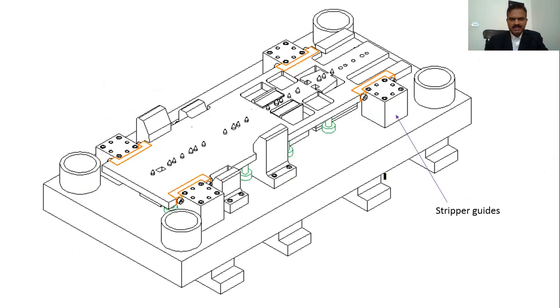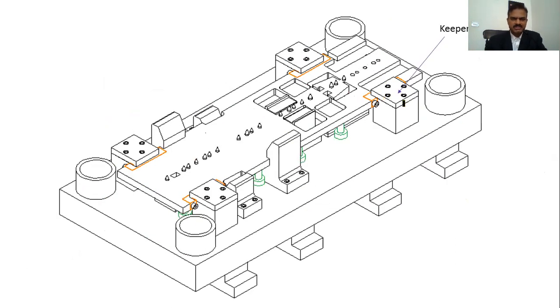You can see the stripper is dropped down now. But in the same way you can move it up, right? Because nothing is stopping it from coming up. So you need to put a plate here that you can see in the next drawing. So this is the plate. See, it's a keeper plate or cover plate. It will prevent it from moving up or dropping down if it is flipped over, right? See the 4 keeper plates here.